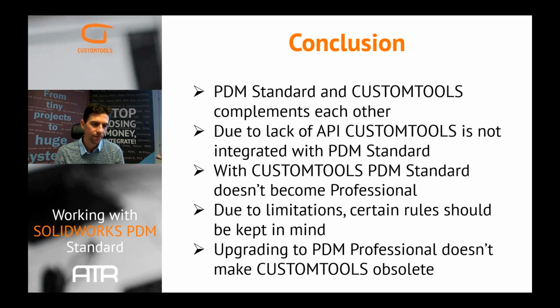So there are still reasons to upgrade from standard to professional, even if you would be using CustomTools, and still you would have a great benefit of using CustomTools, for instance, due to the integrations and tasks. And due to limitations in PDM standard, there are certain rules that you should keep in your mind. For instance, the default values and renaming or moving the files inside the PDM vault.